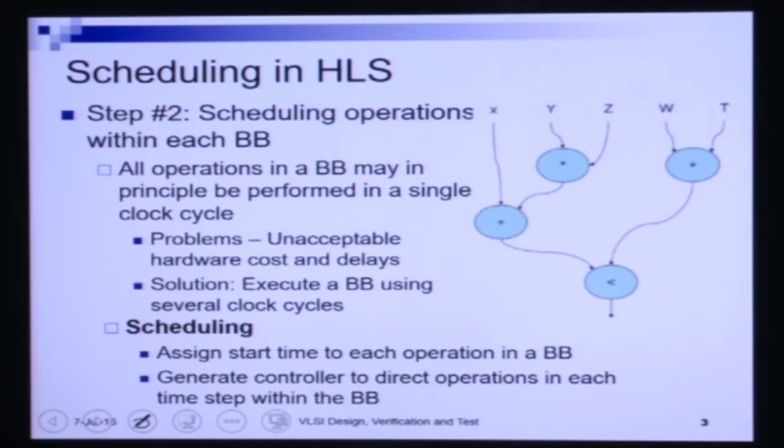Next, we have now arrived within a basic block, and we have to schedule operations within a basic block. Before going into scheduling, we also said this before that all operations within a basic block can ideally be scheduled in a single clock cycle. However, if we do so, then there will be unacceptable hardware cost and delays.